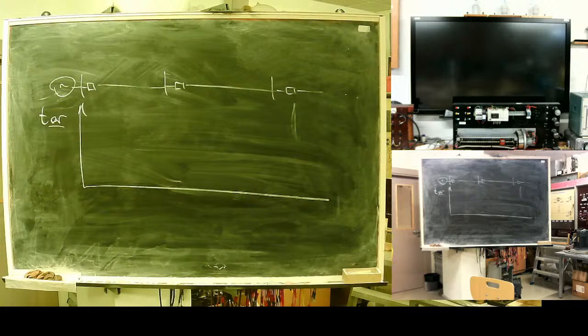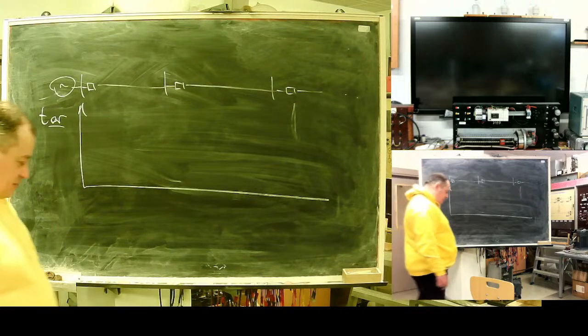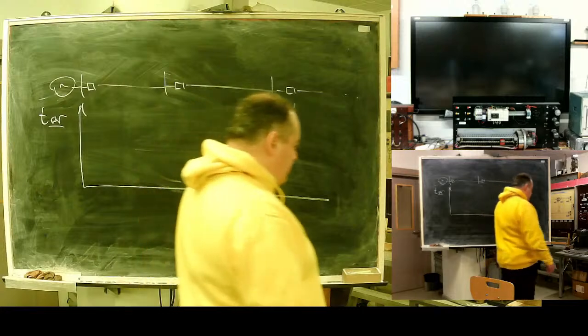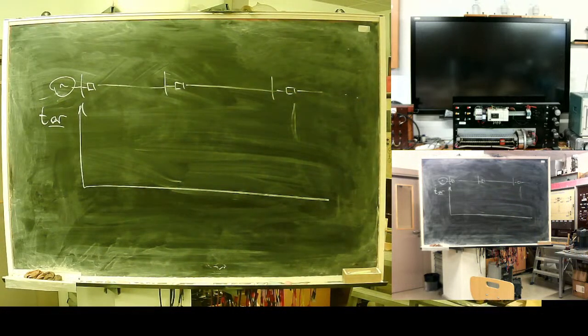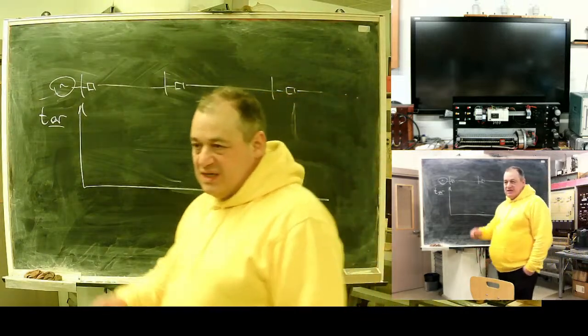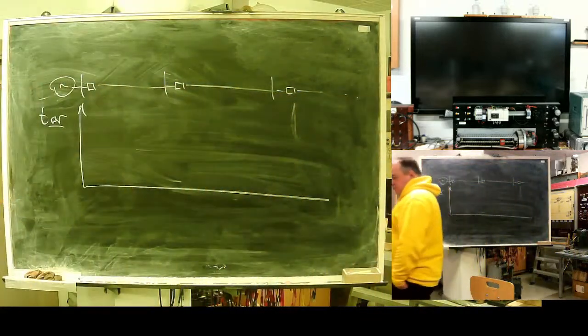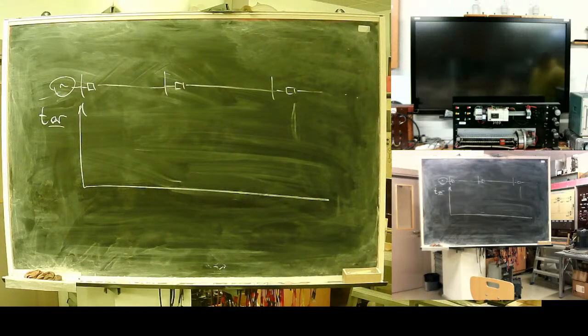This causes a further voltage drop and more consumption of reactive power. So it's a process with positive feedback, and it causes a problem. To prevent it, minimal voltage protection is installed, which drops customers if voltage is below 80-85% of nominal.